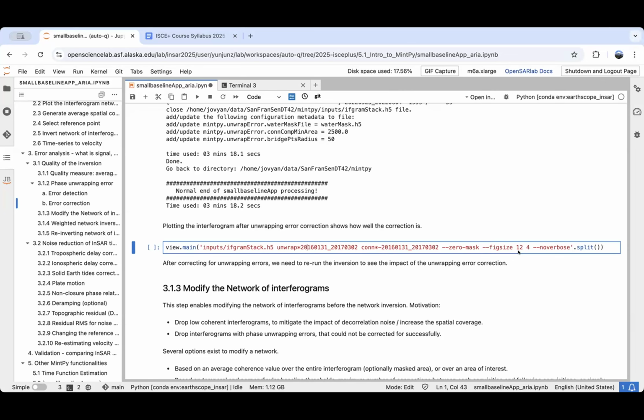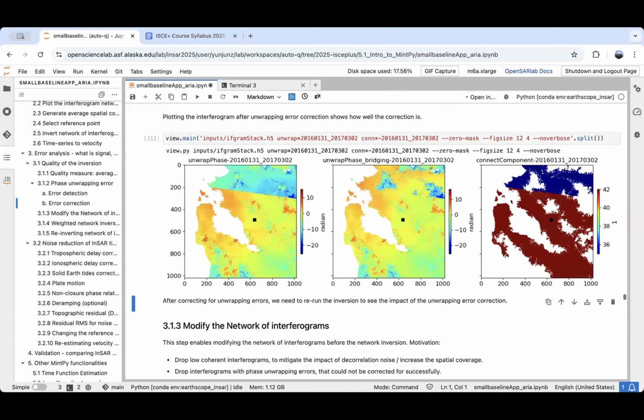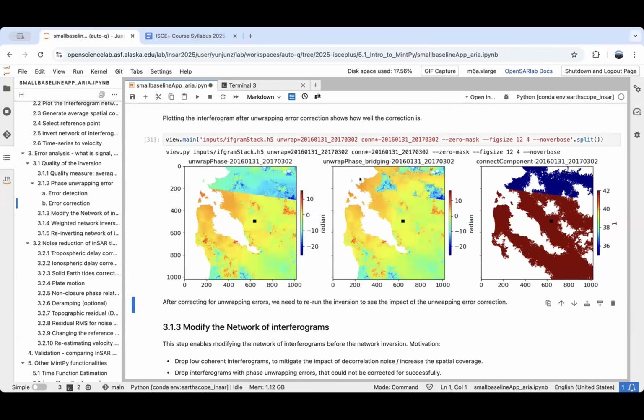Yes. Okay. I think it's more limited maybe by the resolution of your sensor, what's the smallest phenomena you can study. Lots of people use InSAR to look at landslides, very localized features. And in some ways, that's easier. You can place a reference point very close to the site. And the closer your reference point is, the more you can cancel out atmospheric delays. So you don't have to worry about those so much.